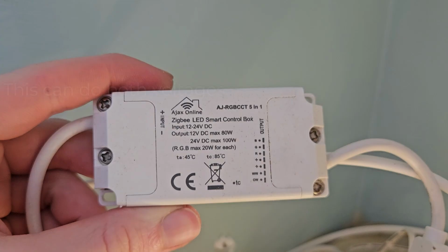Finally, you need a power supply to make it all work. The power supply that you need will depend on the type and length of strip that you have purchased. LED strip typically comes in 12 volt and 24 volt versions, so if you have 12 volt strip, then you need to be purchasing a power supply that outputs at 12 volts. Note that this is also true for the controller, as controllers can come in 12 volt and 24 volt versions, so make sure that this also matches.